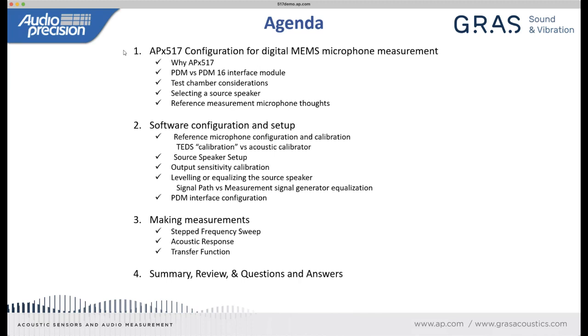And I'll show three specific measurement techniques: a step frequency sweep, an acoustic response with our log chirp, and then our transfer function measurements. I'll talk about why we might use each particular measurement, and then we'll try and reserve some time for question and answer towards the end.